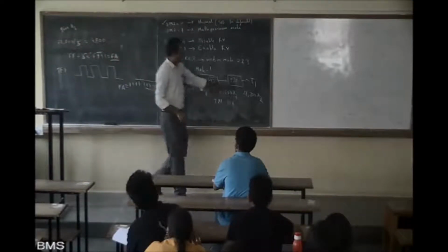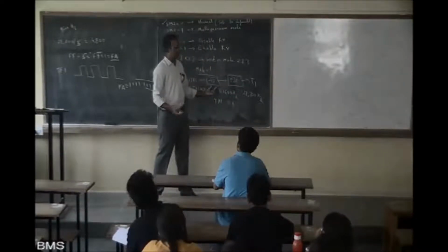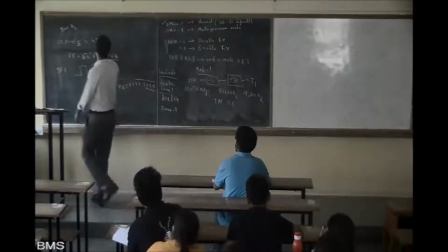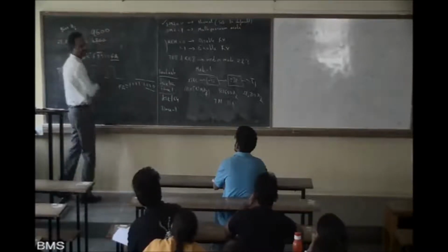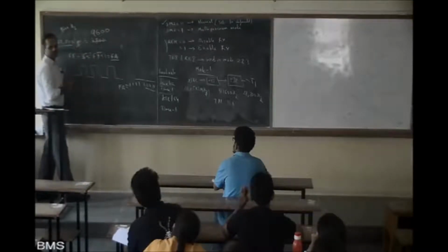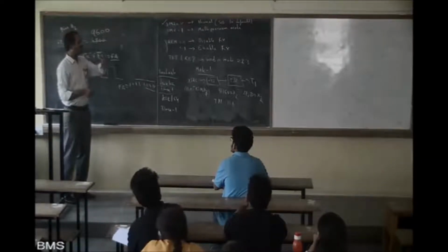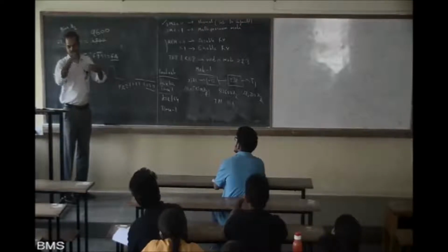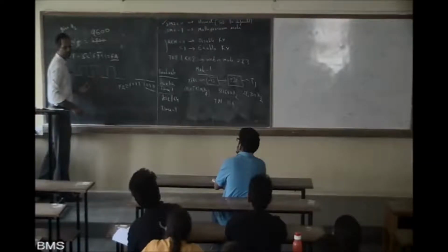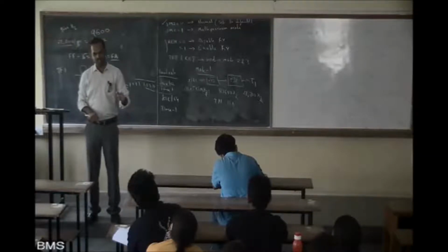For that timer 1, it is divided by 32, added here. Previously we had only XTAL divided by 12 discussed, but it is divided by 32. This divided by 32 frequency is given as 9600. Then you have to divide this 28,800 by 3. This 3 is just 3 counts in the timer. For every 3 counts in the timer, it will overflow and generate the TF1 signal like this. Is it clear? Done?